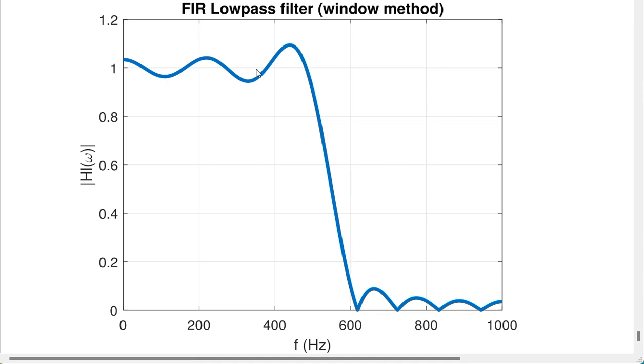The maximum deviation happens here in the passband, and little by little it vanishes. And the maximum ripple happens here near Fs, a stopband frequency, and it vanishes. Okay? We want equi-ripple in passband and also in stopband. But this method cannot do it.